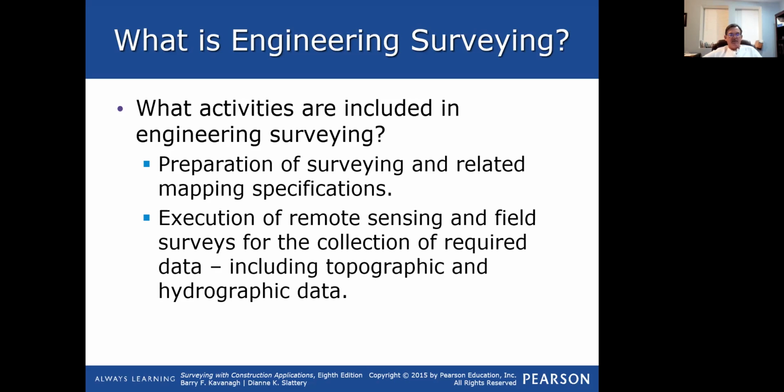I've done that a handful of times in my life. Hydrographic meaning we're surveying the bottom of a body of water. It's done for a few reasons. Locally, it's done more for dredging than anything else, but sometimes it's done for wave protection, so that you just have an idea of how wave action might work during a flood. Another thing is we certainly get topography on the bottom of streams often, so we know the depth of a stream channel as we may put more water into that stream. Can it handle it without eroding? So those are some things we look to do.